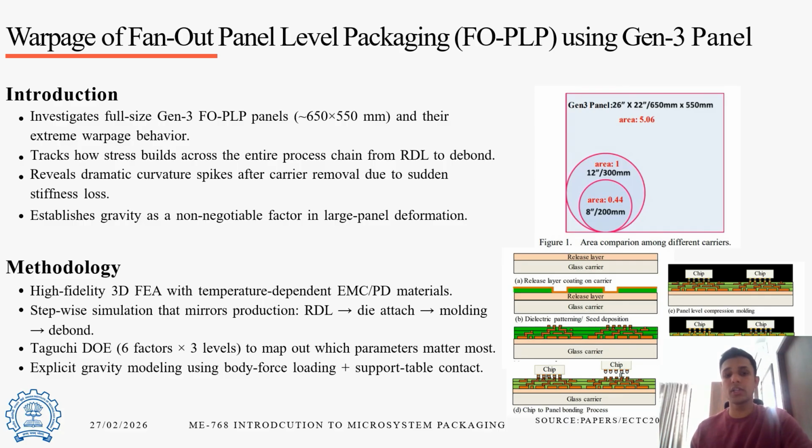The methodology used is high fidelity 3D FEA with temperature dependent EMC and PID materials. He has done a stepwise simulation that mirrors production: through RDL, then die attach, then molding and debond. Also, the Taguchi design of experiments method is used to map out which parameters matter the most. It not only gives the importance of the parameters, it also reduces the computational cost of doing this simulation.